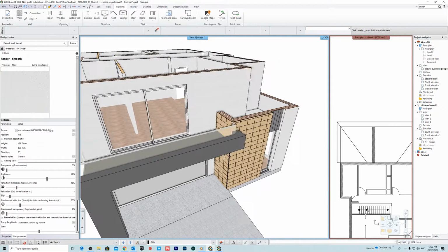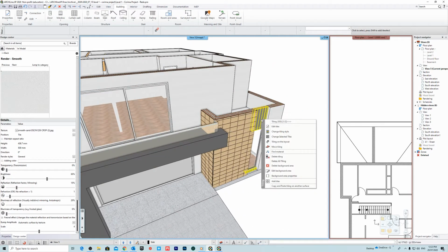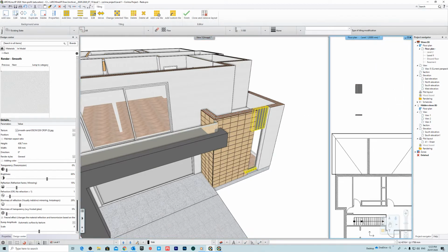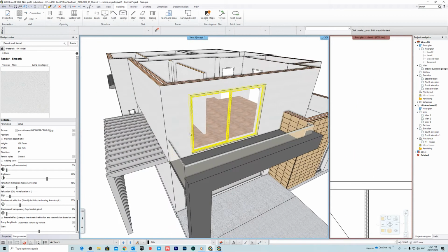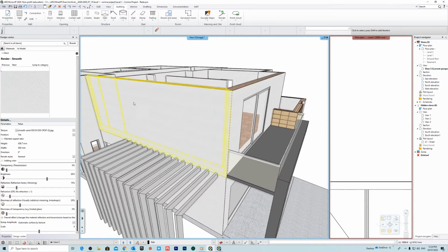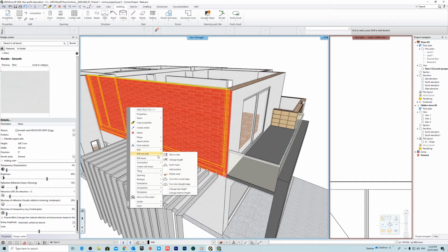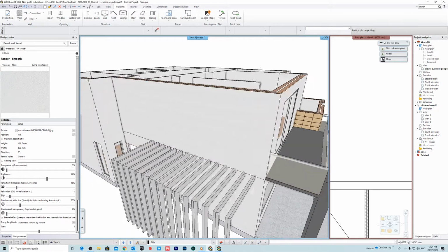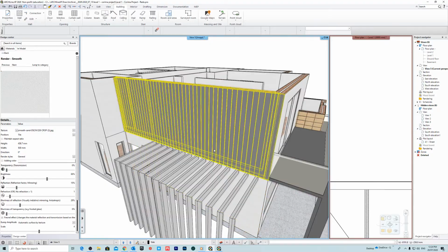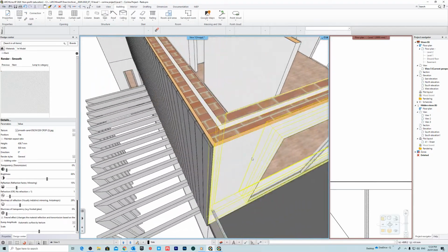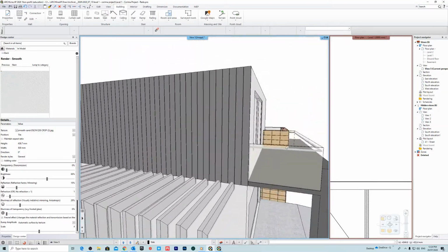Okay, now I'm going to add this cladding again, so I'll right click here, tiling on the layout, hit it right there, and go edit. Okay, I'll go OK and escape, and then I'm going to add my tiling again over here. So I'll right click on wall side, tiling, this wall only, and I'll go OK from right to left. Okay, so we've got our cladding like that.